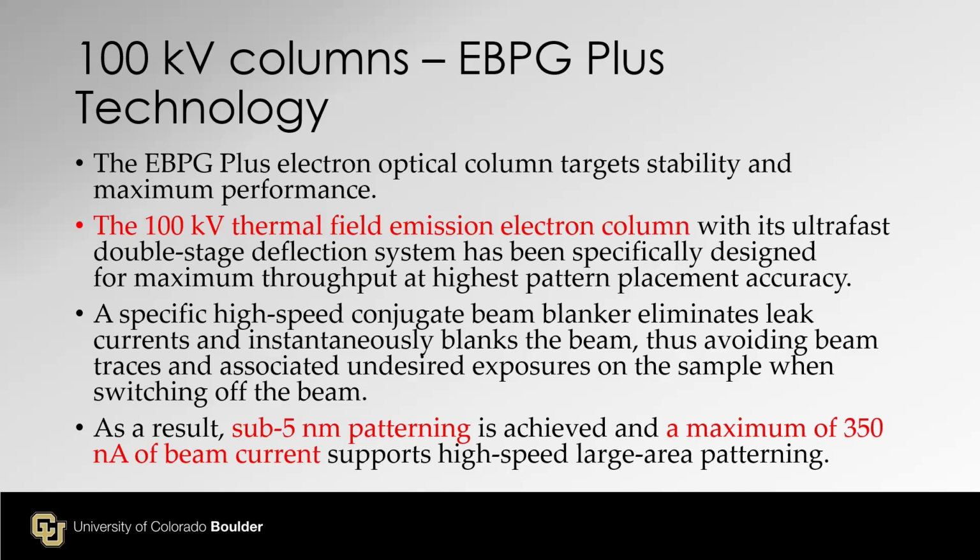For the E-beam writing process, a shorter one goes maybe 10 minutes, 1 hour. Sometimes you need several hours or overnight writing. So stability of the column, beam stability, is super important. We don't want it to change. This is not a requirement for SEM imaging or TEM imaging. Well, if you want to do tomography, it's maybe a difference.